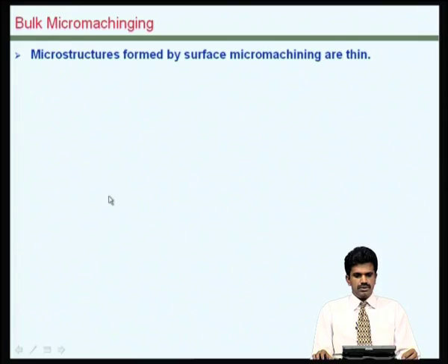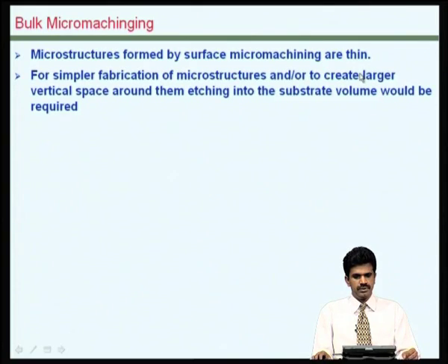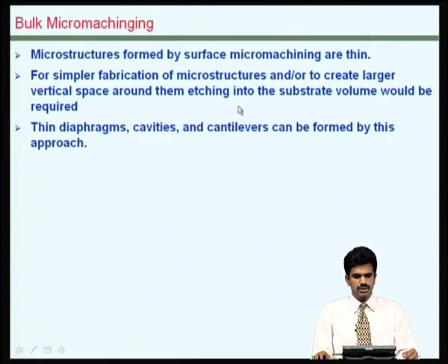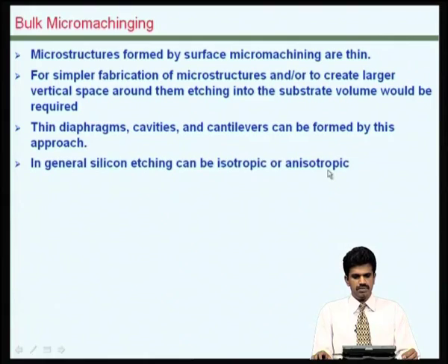In this, unlike in surface micromachining where the microstructures formed are very thin, we can build much larger structures, cavities, or channels by using bulk micromachining. Thin diaphragms are possible. We can even build, as I have seen, cantilevers by this approach.